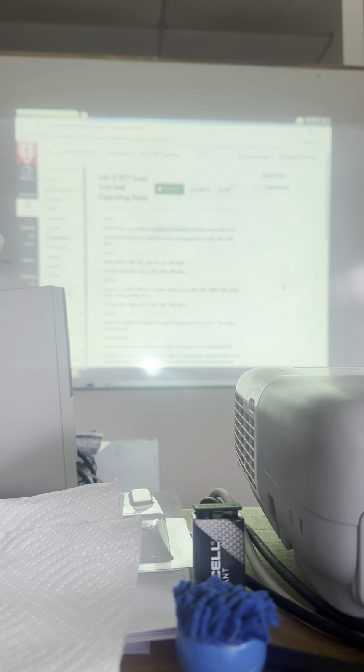So this is my point of reference. I'm going to go below it or above it and drop each point, which means my IC and VCE for the different RBs. In other words, my RBs are controlling my IBs. So, let's say I went for a bigger RB. What do you think is going to happen to IB? Then your point is going to be somewhere in here. Do you agree? Then your other point is going to be here.